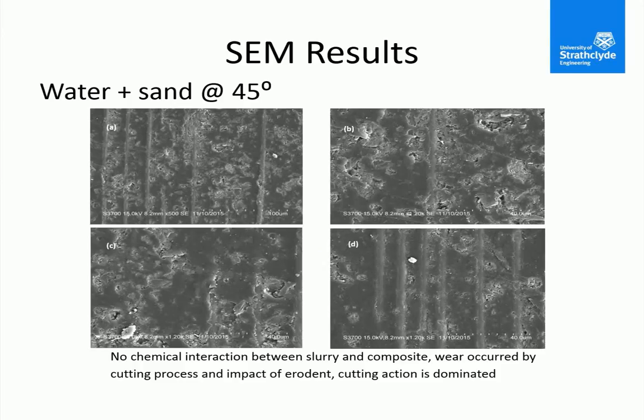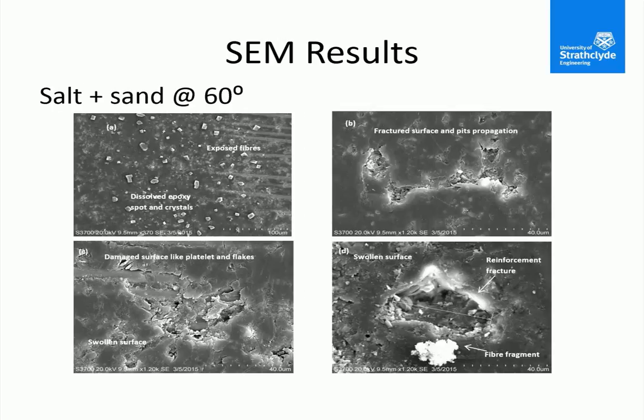Now, what do the micrographs tell us? That's just with water and sand. You see some indentation marks over the surface here. But if we add salt to the system in the saltwater conditions, you can see here extensive cracking on the surface. So we're getting a mechanically assisted cracking on the surface.